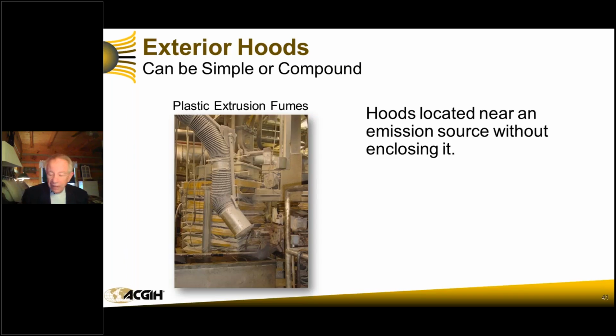Exterior hoods. When do you use them? Well, these are hoods that are located near an emission source without enclosing it. So we would like to enclose it. Here is what's happening: we have a very high temperature, high pressure extrusion hood, and it is extruding molten plastic. What comes off of molten plastic is distillate fractions of polymers.